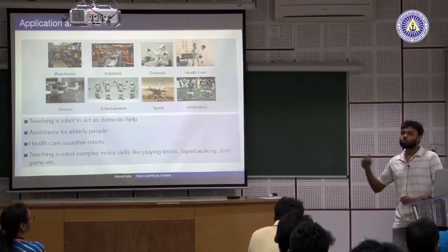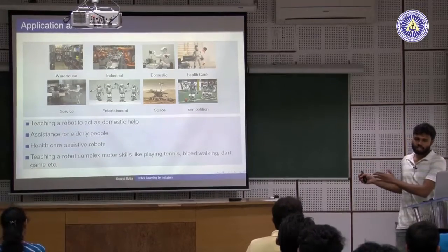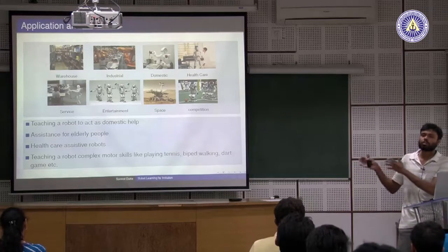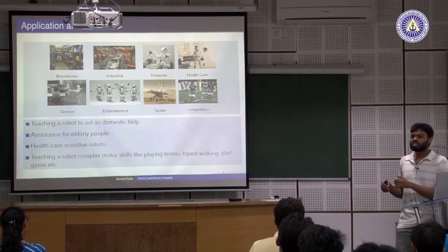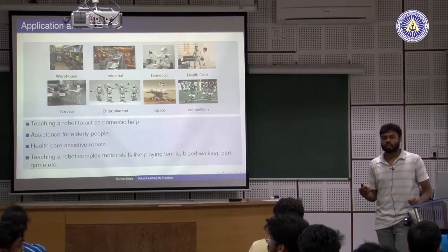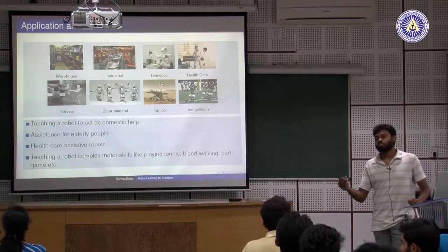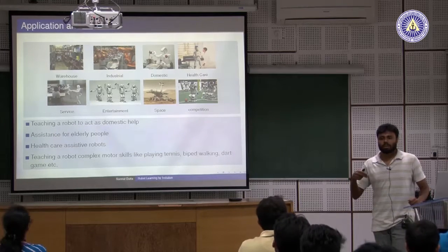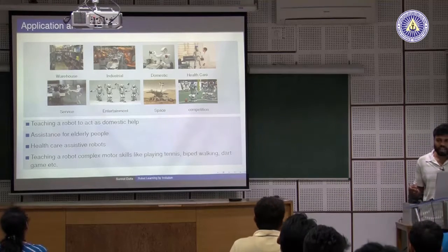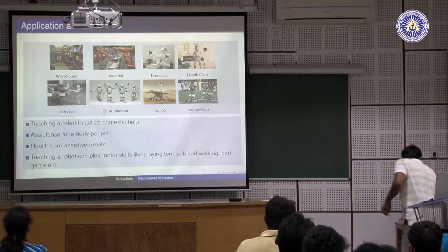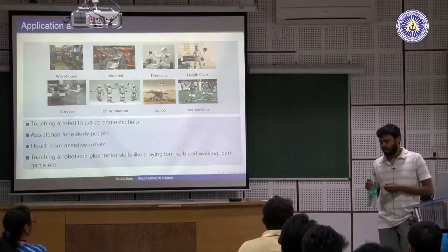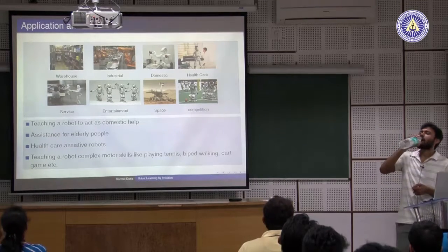I cannot perform that motion at another location in the workspace, because that region of the workspace is not programmed in the robot. So, the robot will simply fail in that scenario. Or say you have pre-programmed your motion planning and an obstacle comes in between, the robot will definitely collide, because it is following the code blindly and is not taking any feedback. That is why we need some mechanism that can incorporate decision-making capability.